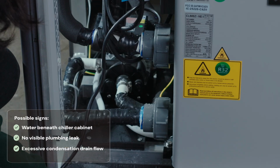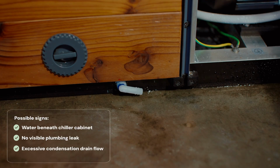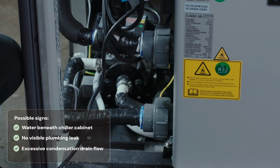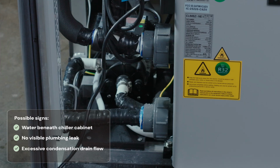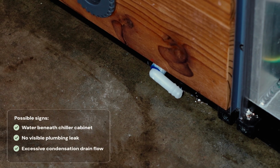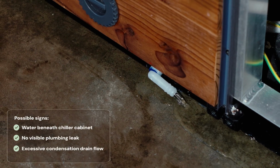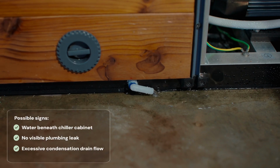Also inspect the condensation drain line, the small white tube connected to the chiller, to confirm it has not become loose or disconnected. During normal operation, the condensation drain will periodically release small amounts of water. A constant or excessive flow from the condensation drain may indicate an internal issue rather than normal condensation.